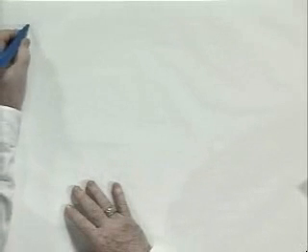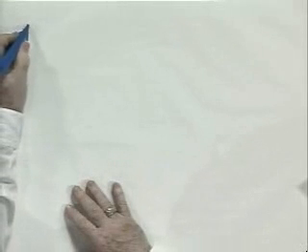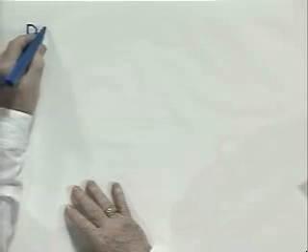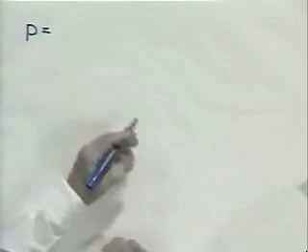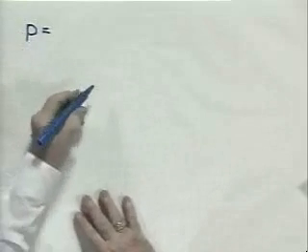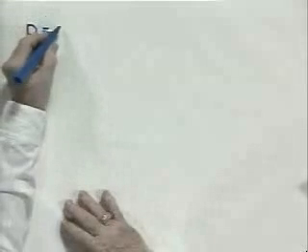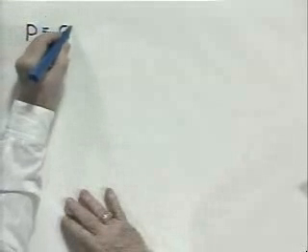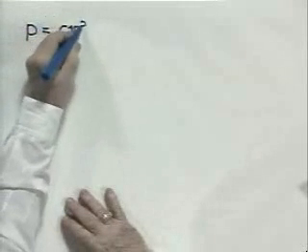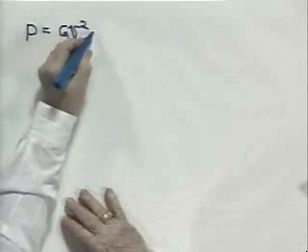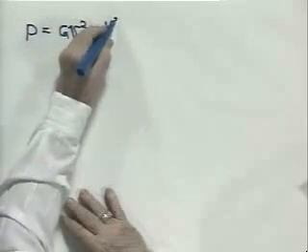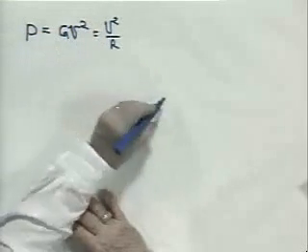Let's look now at the energy loss. The rate at which energy is being lost in the resistor is the integral over some period of time of the power lost in the resistor. Well, the power loss is G V squared, equal to V squared over R, if that makes you more comfortable.